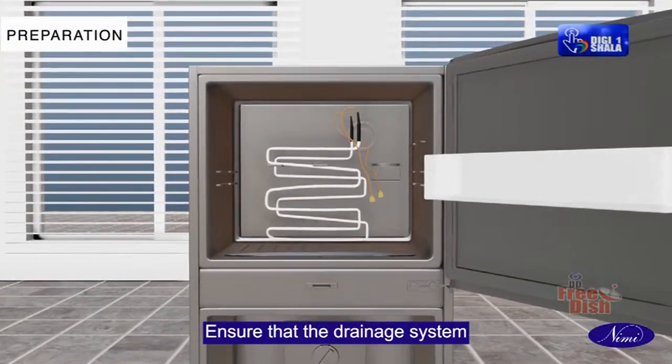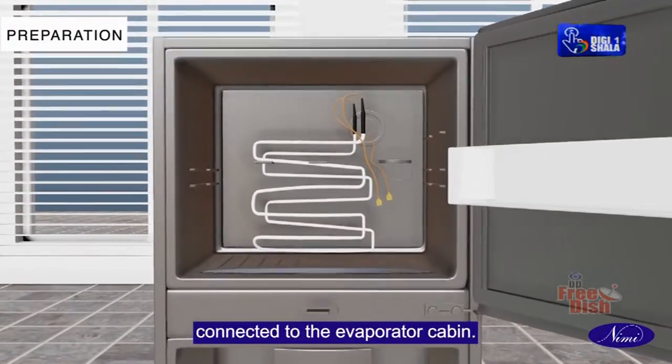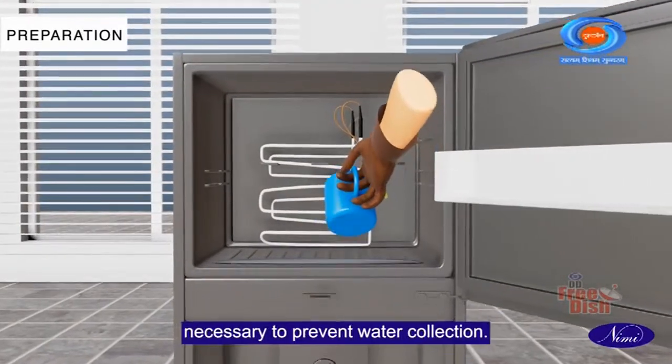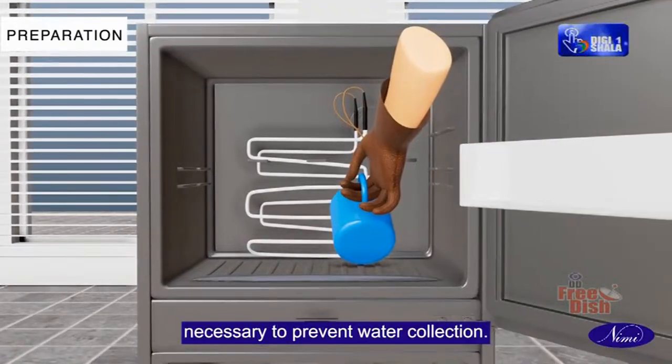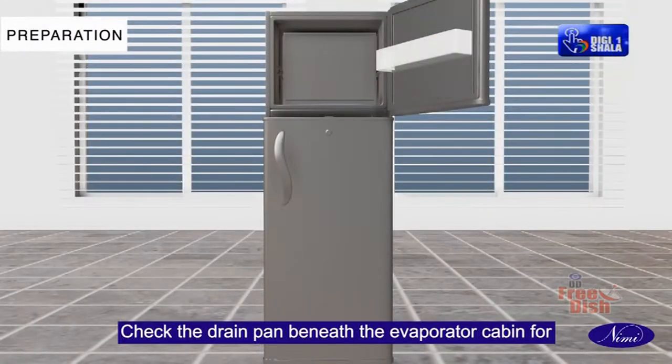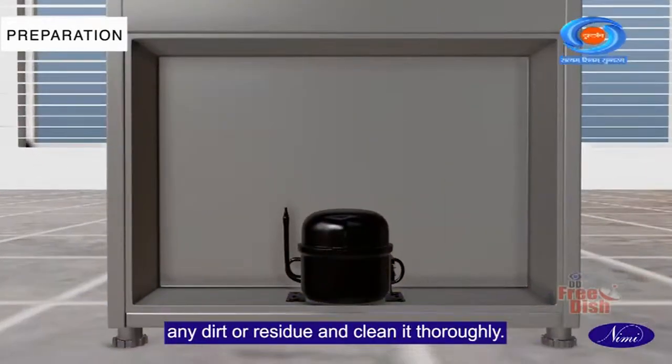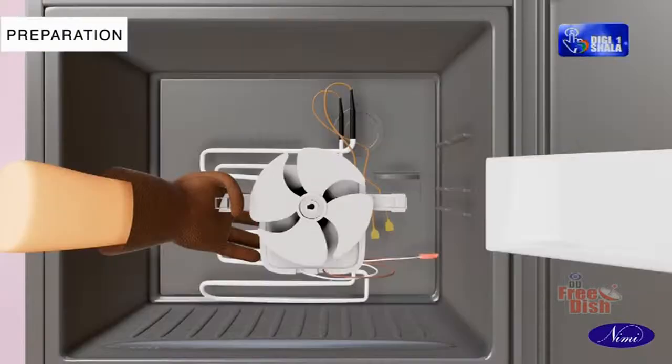Ensure that the drainage system is connected to the evaporator cabin. Clean the drain tube if necessary to prevent water collection. Check the drain pan beneath the evaporator cabin for any dirt or residue and clean it thoroughly.